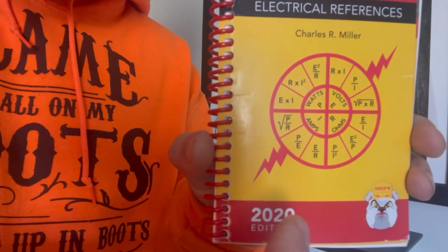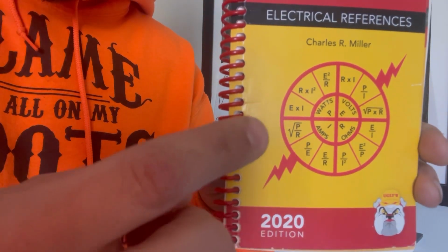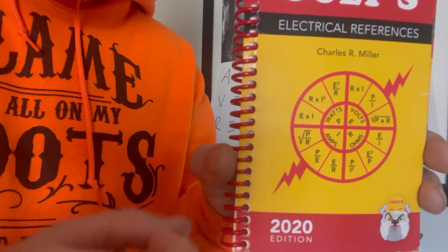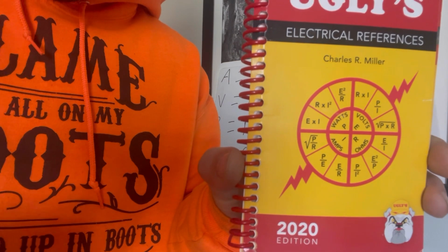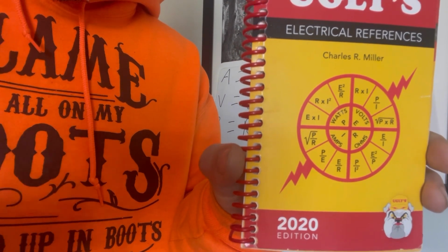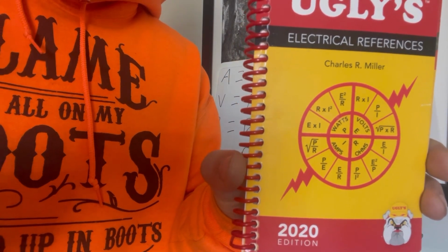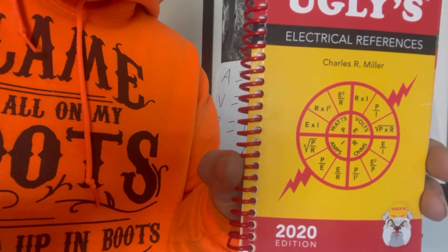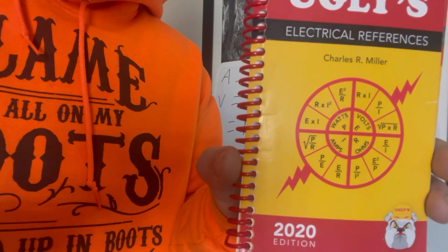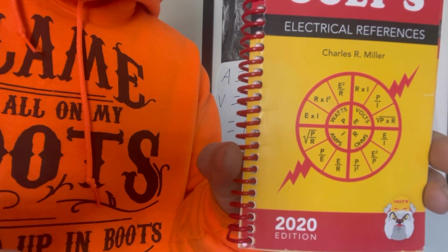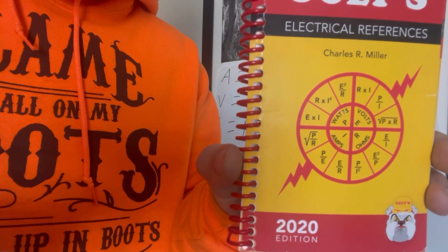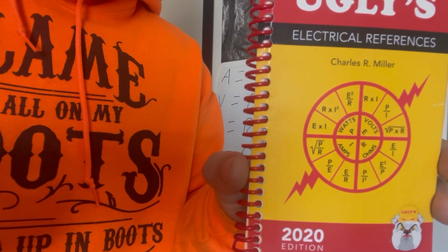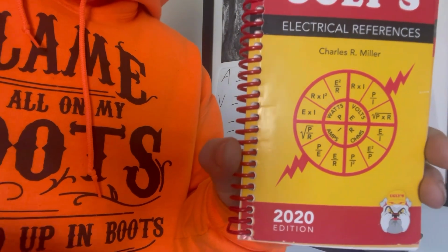If you wanted to get, let's say, your watts, that is equal to your voltage times your current. So if you know you have a 120 volt circuit and you have 15 amps in there, you just multiply that and you know how many watts that circuit is even capable of. So you don't need to go and look for labels. You can just do the math, get your code book, and then size everything up.